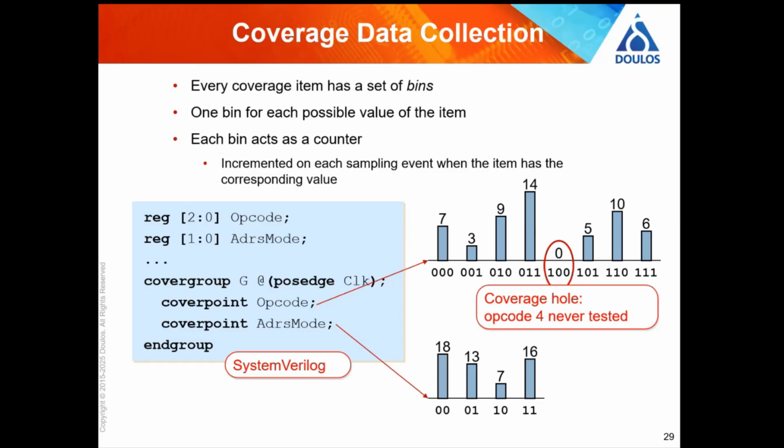So as long as you choose the variables carefully, you can do this grand abstract thing. So you can see this example here, we're probing a variable called opcode. If the DUT were a processor, we need to make sure we've executed all the instructions to make sure we've tested our CPU properly. Then we need to make sure that opcode has had all the values that it should have, for example.